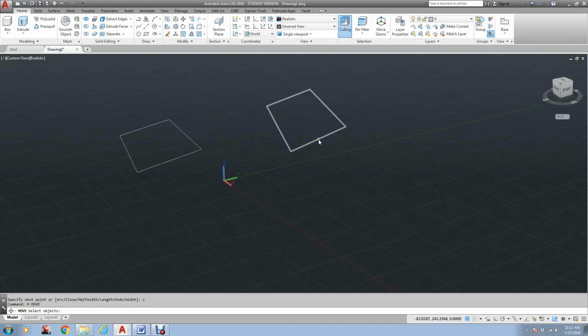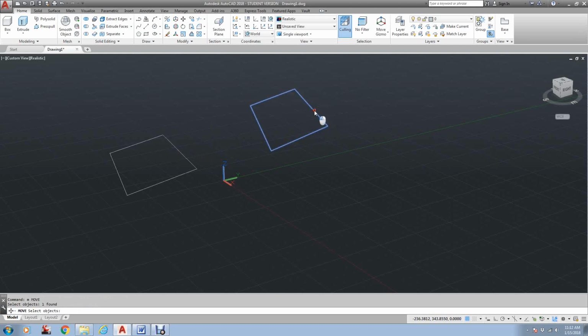If I go to move this, as you see, I just selected it in one spot, whereas here, if I wanted to move it, I have to select it all. I could grab this line and move it over there, whereas if I grab this line and move it, the whole thing moves. When you go to extrude, you can either go up or down, understanding that this is on my surface, which is 0. If I wanted it to go down, I would input a negative number. If I want to go up, obviously it'd be a positive number.